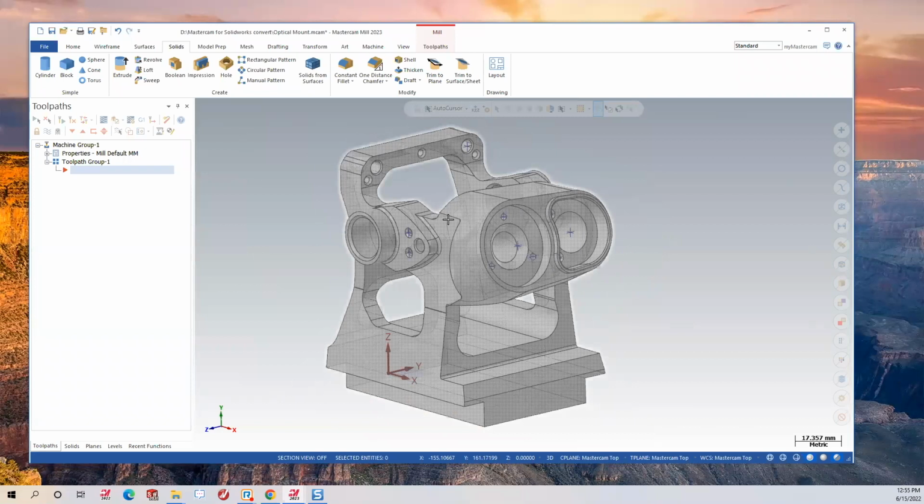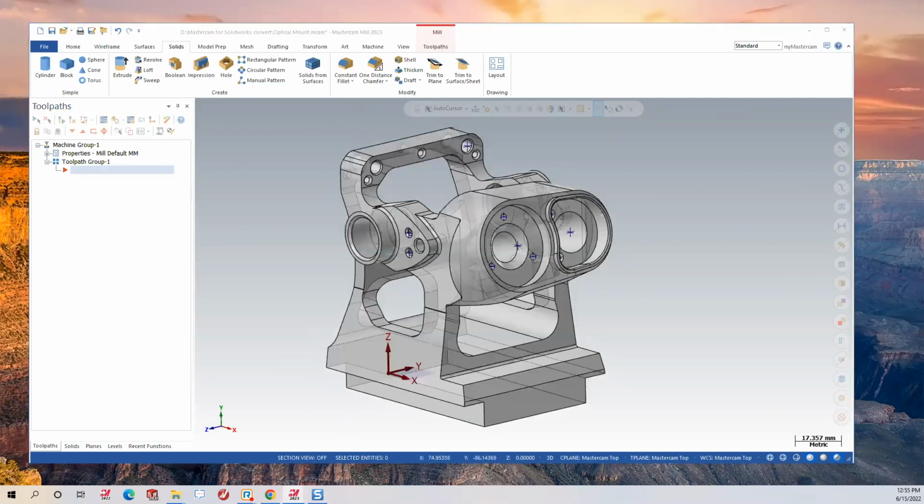If it's not prismatic and it's not a bunch of holes and it's 3D, bring in a model, hit OptiRough and your 3D toolpath, generate a toolpath, and move on. I question how many times things change in engineering that you have to go back and redo stuff, where I don't think the chaining of the geometry may help you save a little time. So far, I think that's what I had for my presentation.